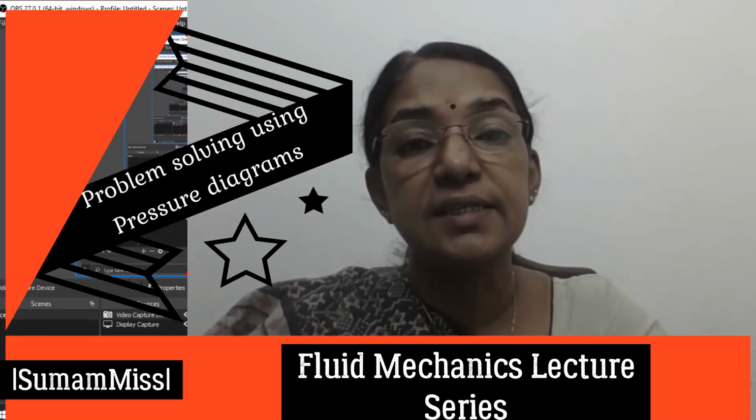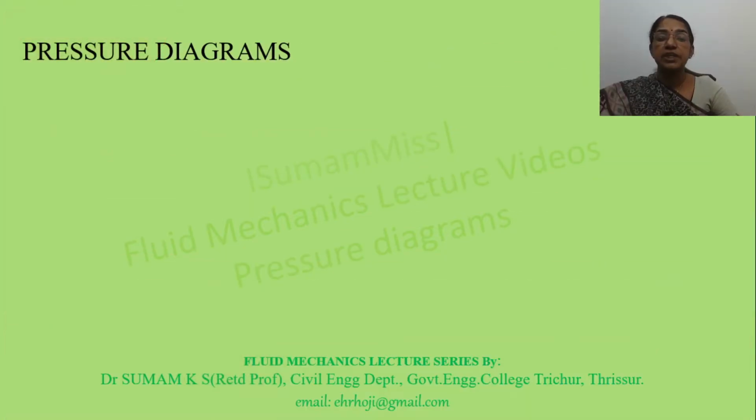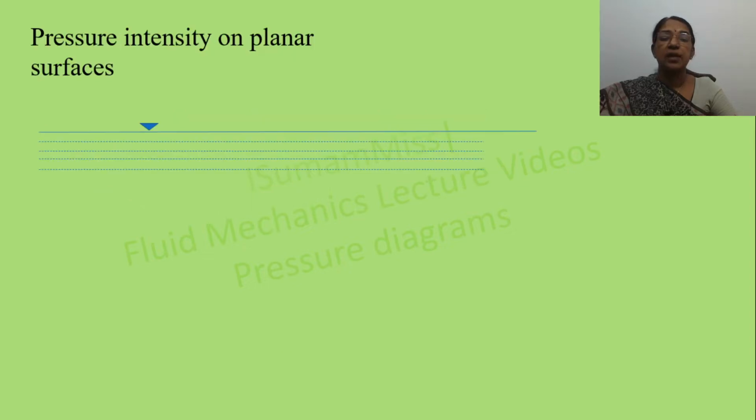The topic for today's discussion is pressure diagrams. What is a pressure diagram? A pressure diagram is the graphical representation of variation of pressure intensity over an immersed surface. How is it prepared? It may be prepared by plotting the pressure intensity at various points on the surface.